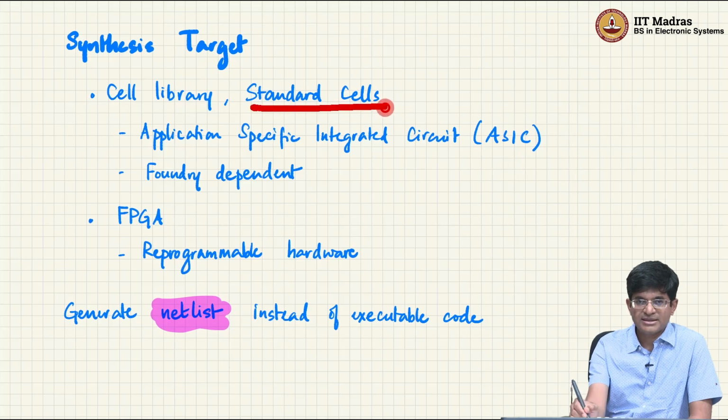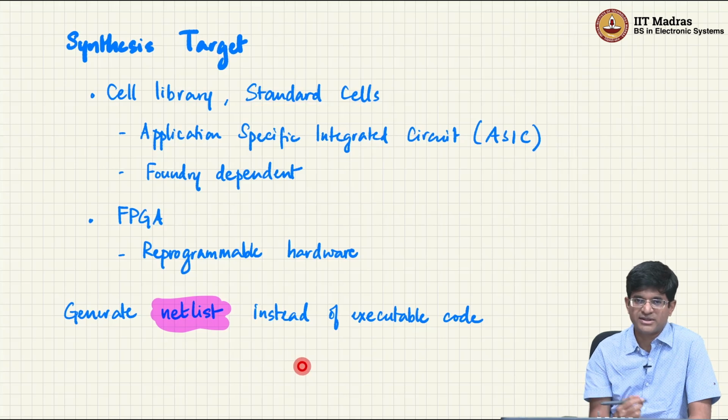And these standard cells, right, which could be AND gates, OR gates, but they could also be AND gates of different sizes, right. Even a NOT gate, an inverter, you will find that in a standard cell library there are probably 3 or 4 different variations of inverters. Why? After all, they all perform the same logical function, but that's where reality kicks in and we find that there are actually delays associated with gates, there is power consumption, there is area, and all of those factors need to be taken into account, and because of that we provide multiple different variants of the same gate that occupy different amounts of area, that have different speeds, different power consumption, and finally end up giving you different final costs for the design that you are trying to make.